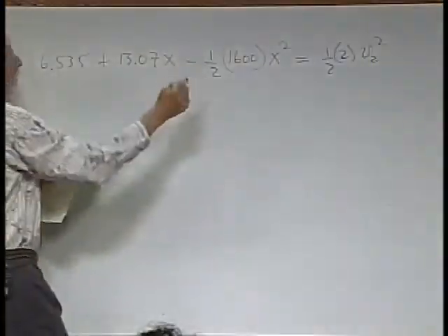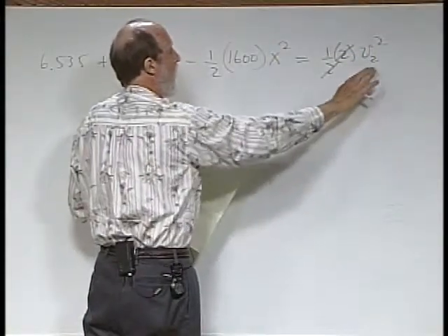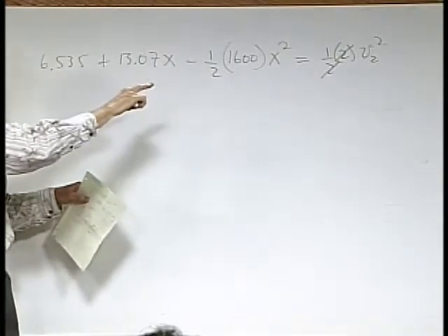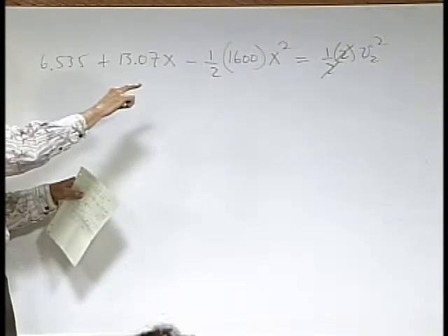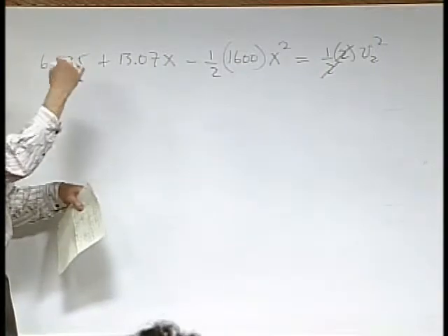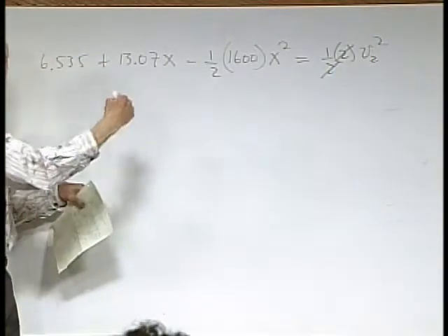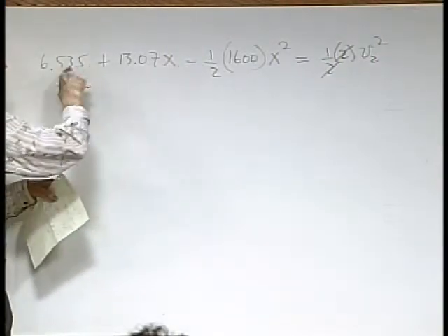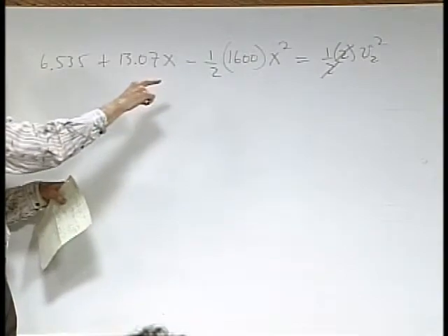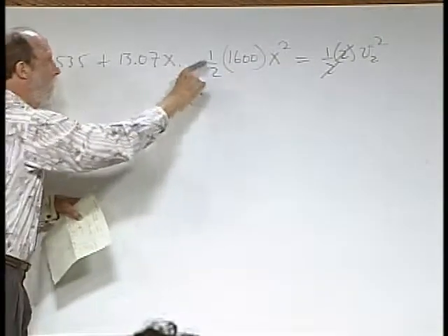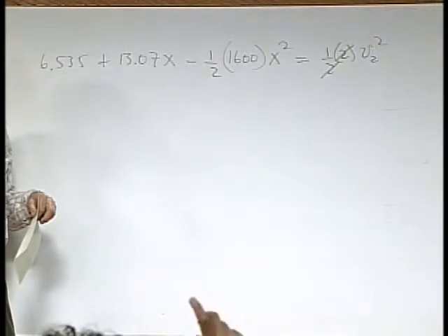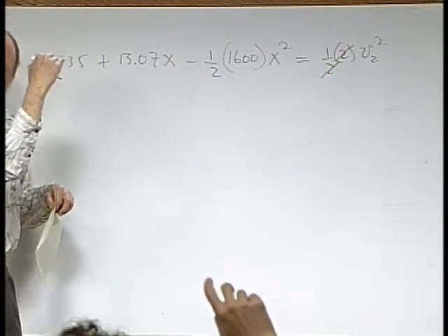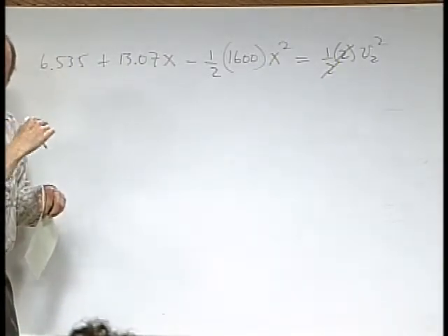So what I wanted to point out here, notice the 2's disappear over here on this side. So this is the square of the velocity during what portion of motion? From the beginning until some time, during the spring is active in compression, isn't it? And so this behavior is quadratic. This behavior is quadratic, as a function of the deflection of the spring. And then you take a big old square root on that to obtain the velocity as the spring is displacing.